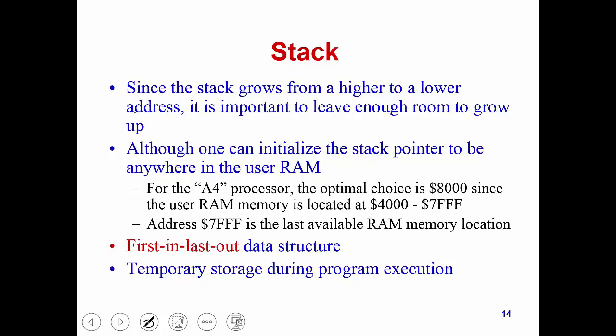If you hope to use a large number of memory locations as stack, but the number of locations is too few and not enough, then you get trouble. In general, one can initialize the stack pointer to be anywhere in the user RAM or memory. Memory can be ROM or RAM, but here the stack can only be RAM.